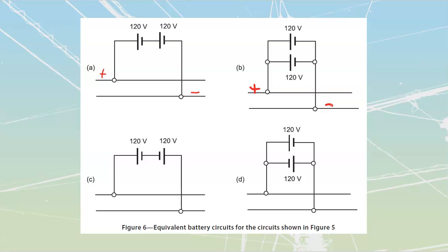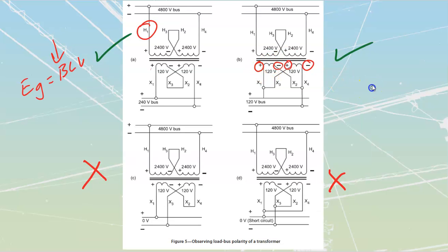You'll note that for both of these characteristics, whether we're looking at the series or at the parallel, we will be able to develop full VA out of this, right? If you take a look, we know the ratings for this one, we did that earlier, were 416.7 amps for each one of these individual windings.